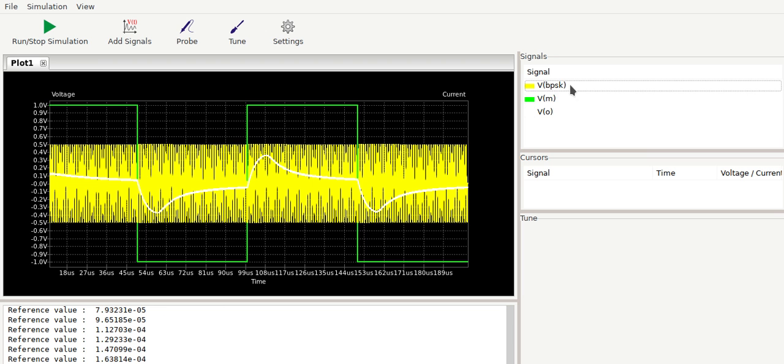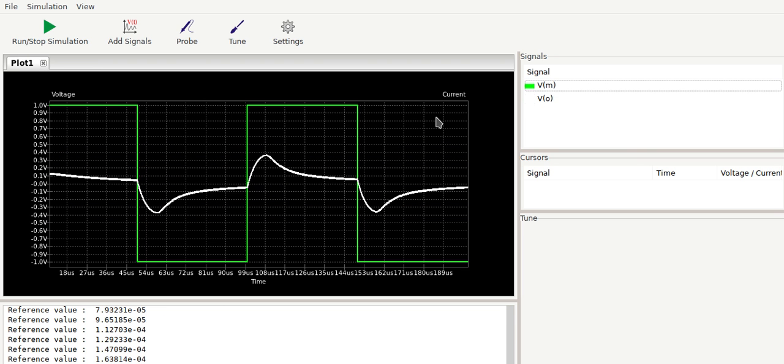So I'll remove the BPSK signal, and keep the demodulated output waveform and the modulating signal alone on the screen. And from this it is clear that we can easily convert this into a 1/0 format or defined voltage levels with the help of a comparator with fixed thresholds.